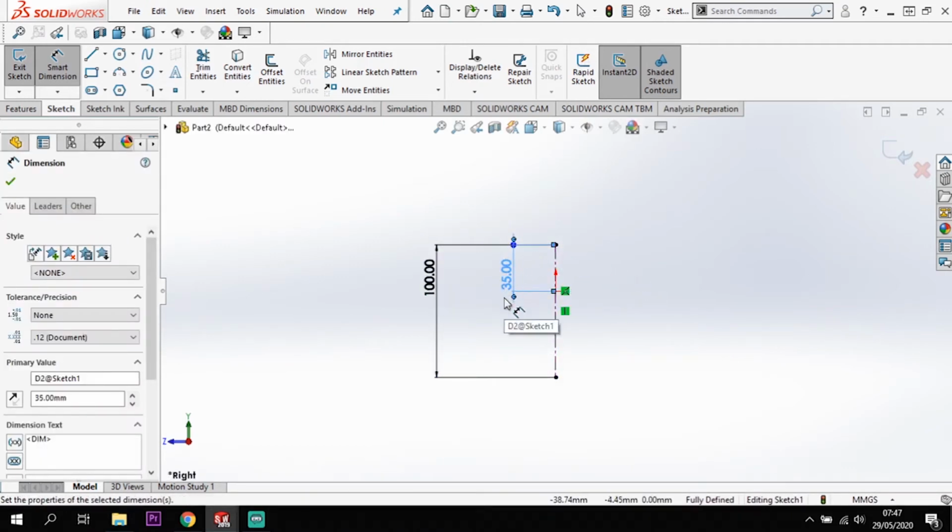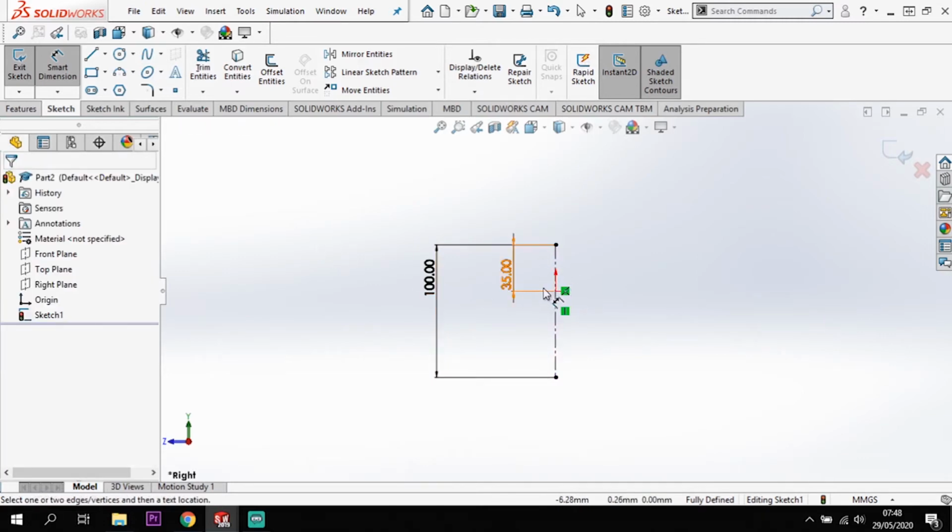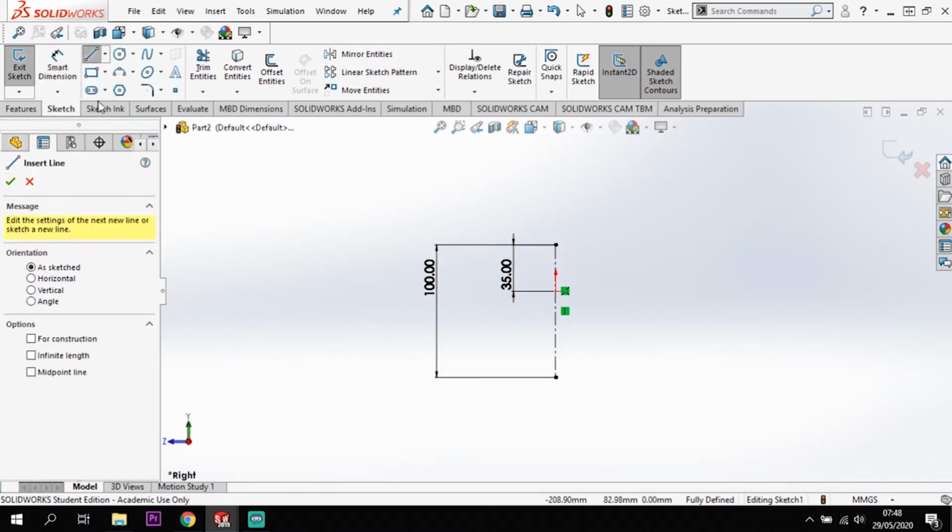Now it's a good idea when you are modelling, before you start just creating the shapes, plan out where you think things are going to fit in compared to your planes. If you aren't planning it out, when you get there, you're probably going to end up having to add in more planes rather than just use the existing planes that you've got, which is just going to slow you down a little bit and make the whole process just that little bit slower.